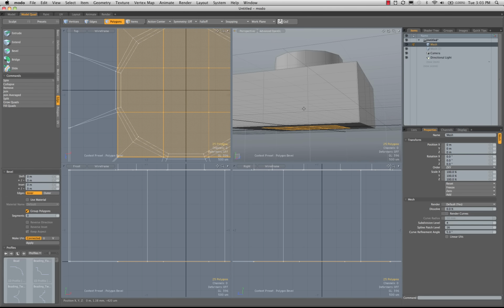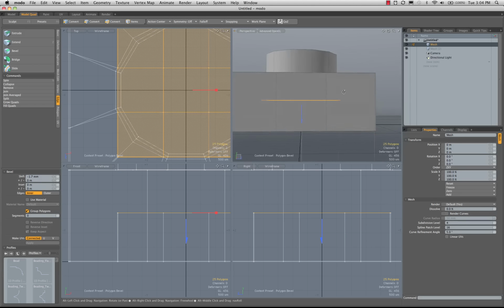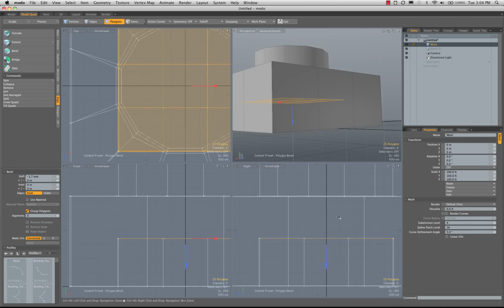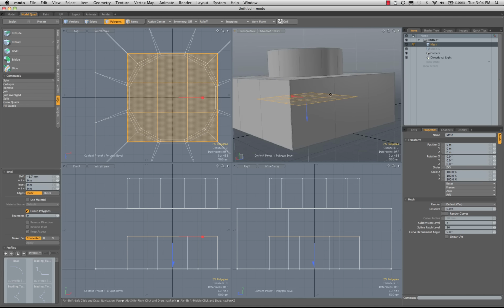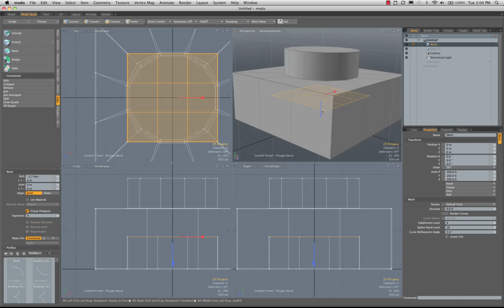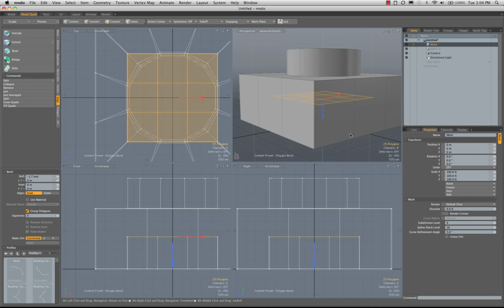Now again, I'm going to go to the bevel tool, and this one we're not going to inset anything, so we can just drag straight up. And we know that the height of that button on top is 1.6 millimeters. However, if I go up exactly 1.6 millimeters, again, we end up with these little intrusion problems if we put a couple of pieces together. So just to keep things nice and even, I'm actually going to go up to 1.7 millimeters just to give it a tiny bit of clearance. And that will help keep things working better when we go to render, especially clear pieces. So let's see here. That works pretty well.